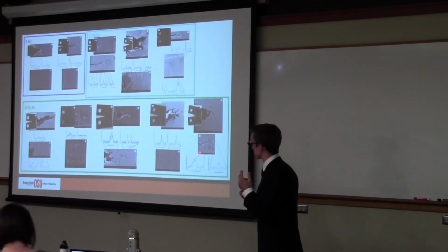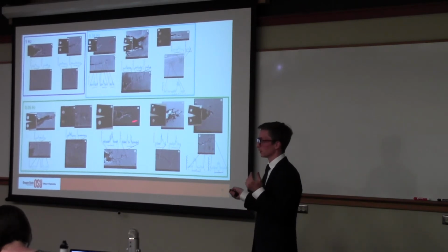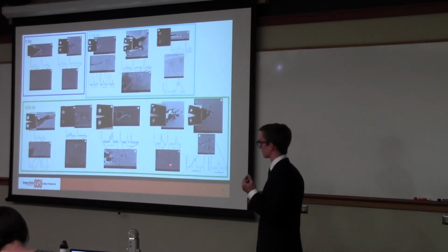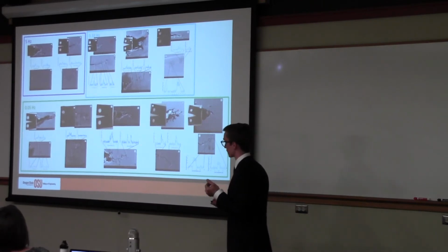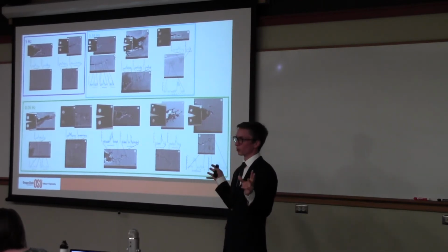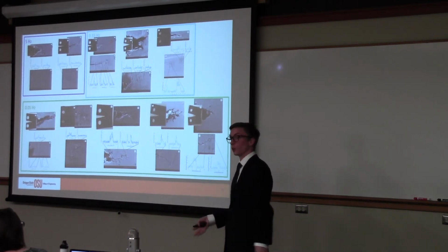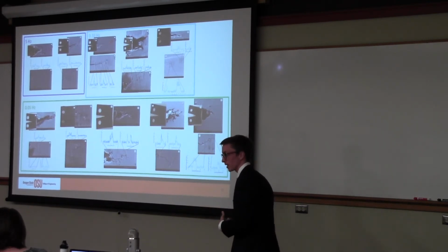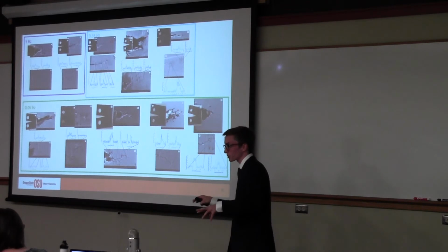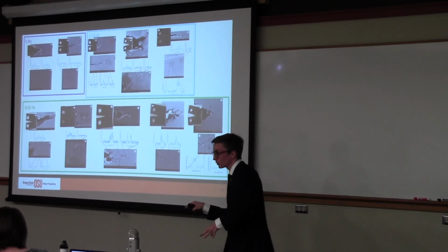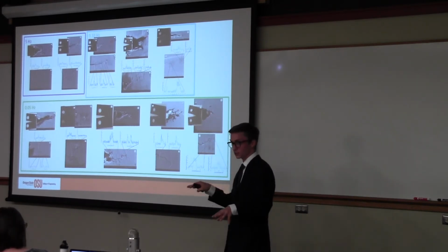So we know that it doesn't matter for higher stress intensities because oxygen's going to fill up the entire crack tip, but for lower stress intensities, we might need to do some more tests in impure helium to figure out what the effects are of removing the protective oxide, but still having maybe enough partial pressure of oxygen to do some dynamic embrittlement mechanisms, because that stuff can mess you up.